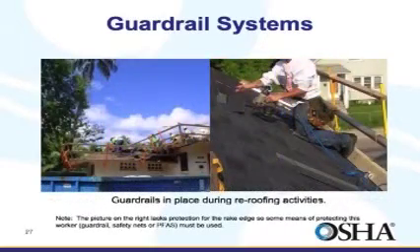In this slide, we see re-roofing activities being performed behind guardrails. The picture on the right lacks protection on the rake edge, so another means of protecting this worker, either safety nets or a personal fall arrest system, must be used.